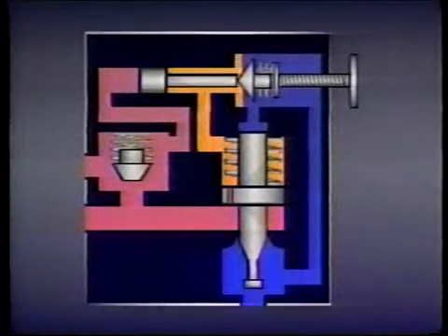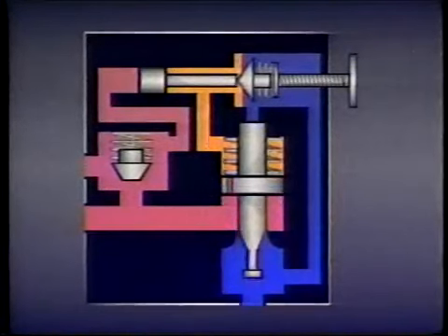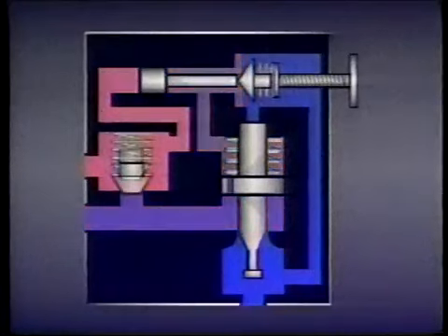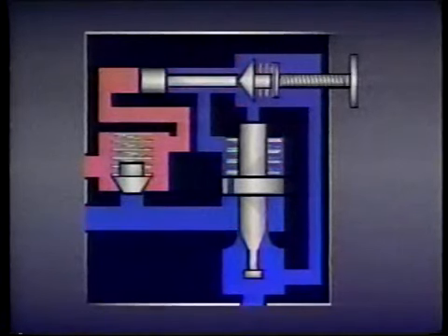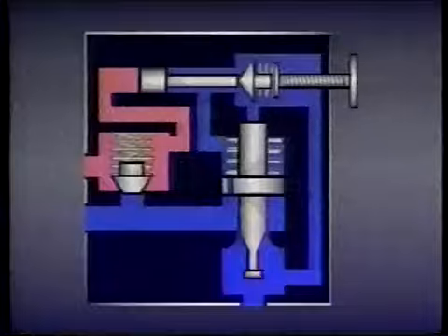In this way, a differential unloading relief valve allows the pump and motor to unload when an accumulator is filled, and to remain unloaded until the accumulator needs to be filled again.